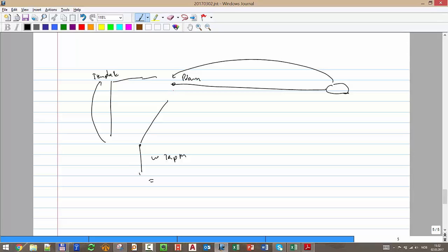Yes or no? Yes, yes. Depends, okay? For well M, I have a fully open choke. I'm not choking the wells from template M, so I can continue all the way to the suction of the compressor. But what happens with template L? The solution that the engineer provided was to choke the templates of well L, okay?